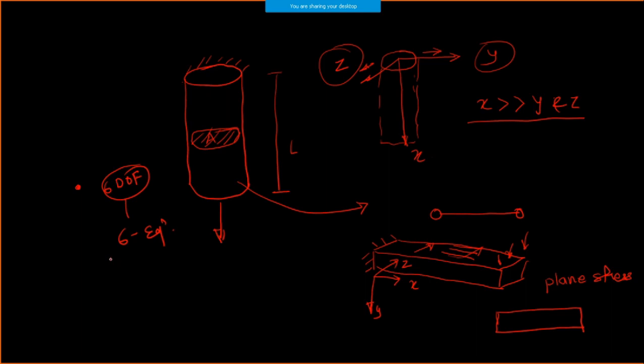If I do a 1D analysis, I have one equation for a single point in space, or I can say a node. And if I have a 2D analysis, I have two equations. Likewise, I'm going to reduce the number of equations and get faster calculations. That is basically the intention. That's the reason conversion of a 3D model to a 2D model is important.